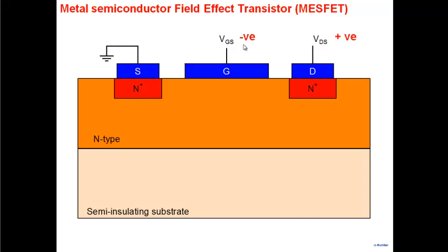Say I apply a negative voltage and a positive voltage here. So if you apply positive voltage, forget about this for a moment. If you apply positive voltage, what will happen? Electrons will start from here. This is a good contact, so there'll be very little voltage drop here, they flow through the N-type semiconductor, and then will come here, right? So that's the path of the current. Except that there'll be a depletion width here, right?